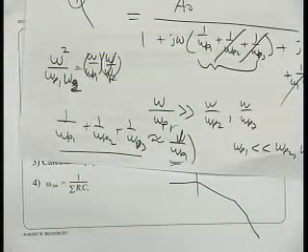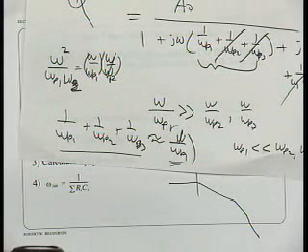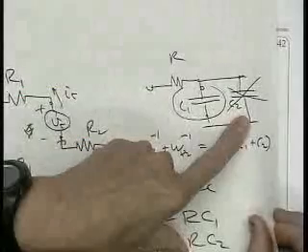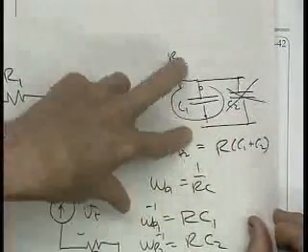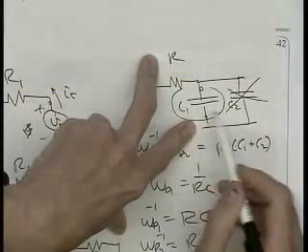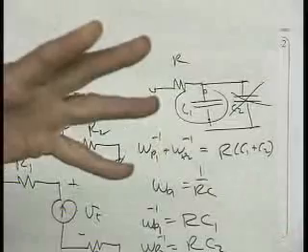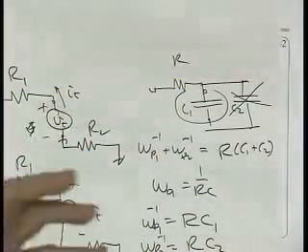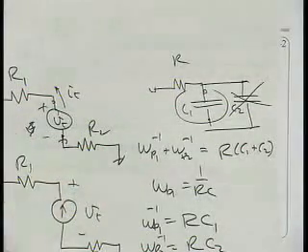If you're going through and calculating the RC for every one of them anyway, when you find it, why do you have to sum it up in the end? That's extra. Well, maybe you have a situation like this, right? You need to add them all up because you may have a case where two capacitors are contributing to the same pole. So these may be on the same order, and you want to take care of that case. But actually, you've hit the right answer here. This helps you a lot to figure out where probably the lowest frequency pole is.